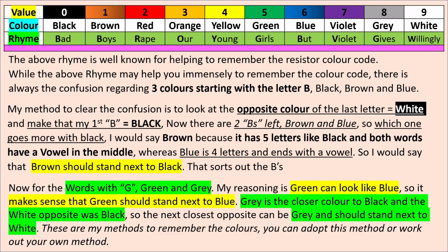But the moment I go to the orange, yellow, and then I go say brown, then I have 1 zero behind there, so it'll be 340 ohms. If it's a red color afterwards, it will be 3400. If it's say a white color afterwards, it would be 3, 4, and 9 zeros would be attached off that, which would mean it would be a very big resistor. Okay, so hopefully that will allow you to remember why this color coding band is there.